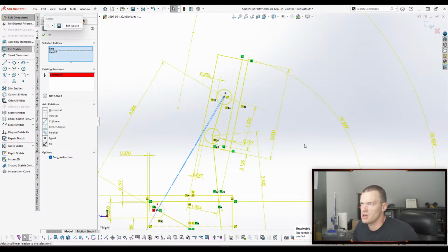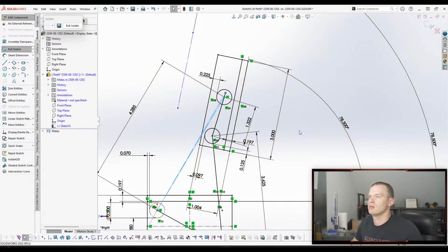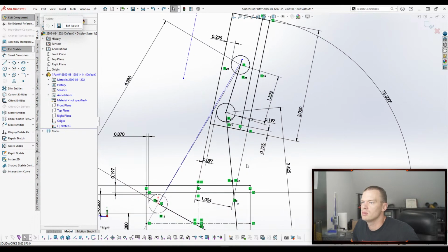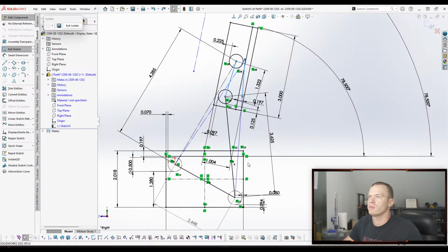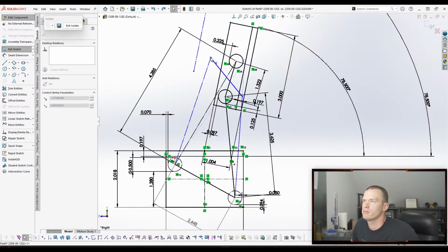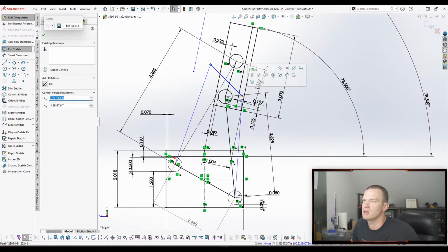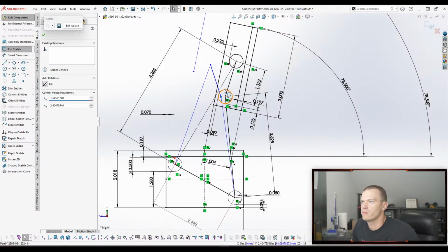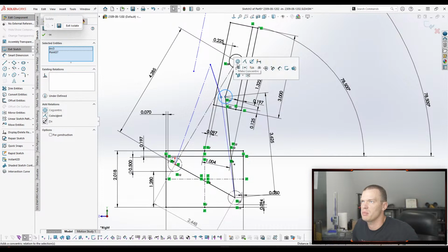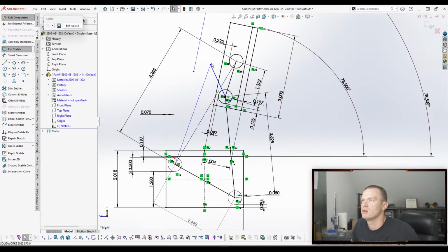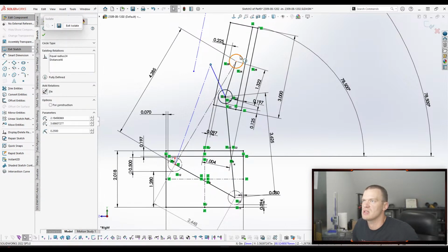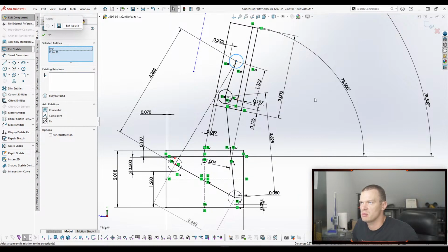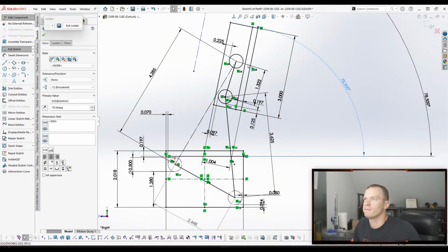And basically what I'm trying to get is I want these points to be in the right spot. Maybe that's the way to do it then. But I don't want them to end up being the same points. And if you use coincident, SolidWorks will compress them down to be the same points. Yeah, see, it just got rid of that line.